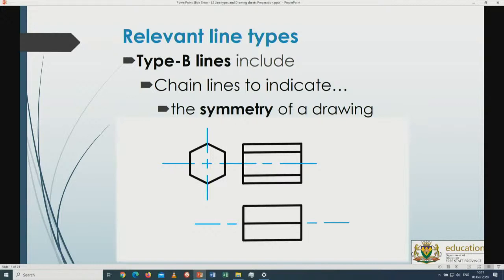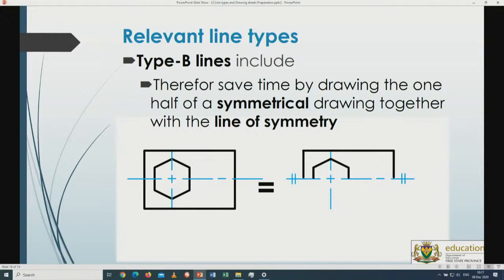And then there's also something you can take note of that you never knew before, I believe. When something is symmetric, in other words the upper part looks exactly the same as the bottom part, then you can keep the center line and just draw 2 lines at the ends on either side of the drawing. That symbol is indicating that the drawing actually carries on to the bottom.